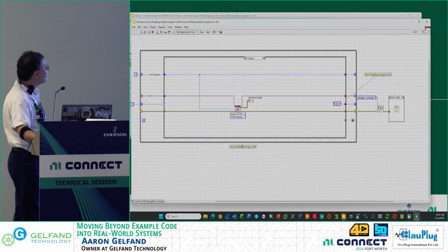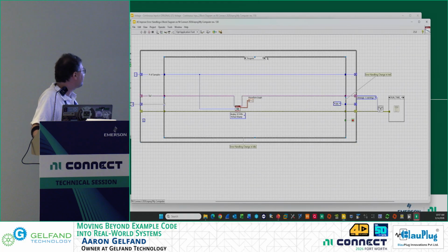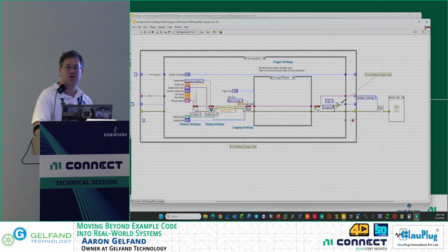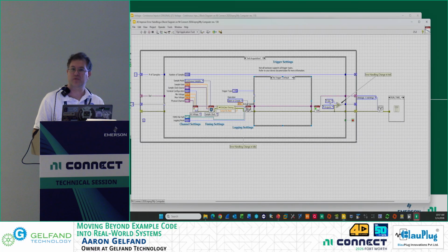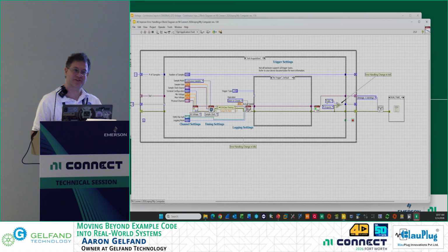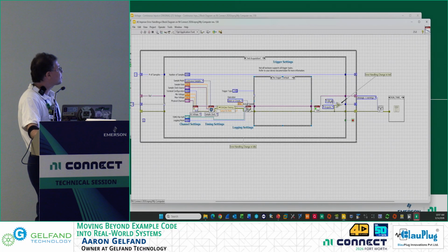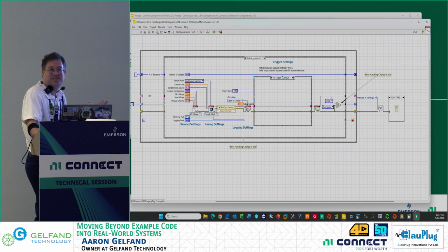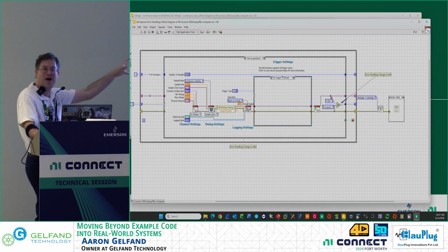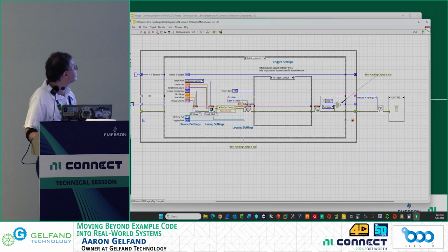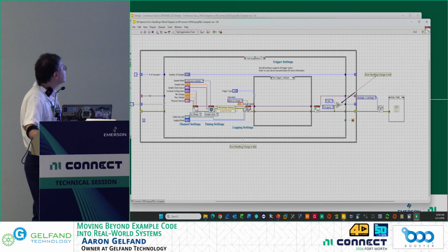Now what we've done, and I gave myself some notes so that we can make sure that we see them, is in my initialize acquisition case, I don't automatically go to acquisition. I don't know that I was actually successful in the previous version. Here, we say, if error is true, we just go back to the idle case. We weren't successful. There's no reason to continue and try and throw up bad data. And if we were successful, meaning there was no error, we can go ahead and start. So we make an error handling change here.